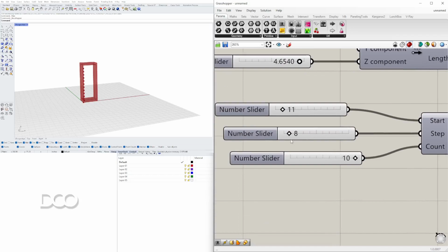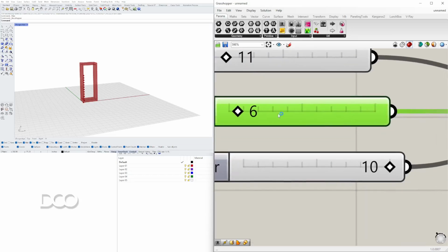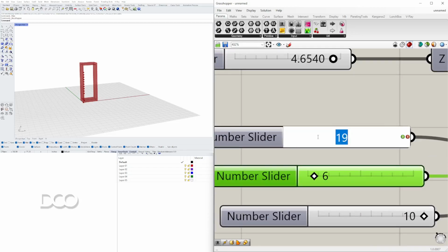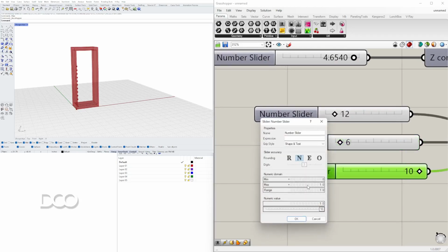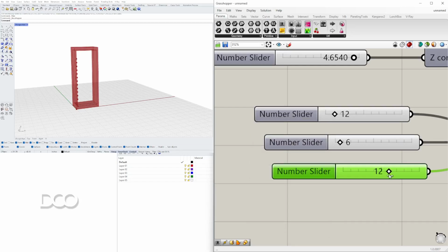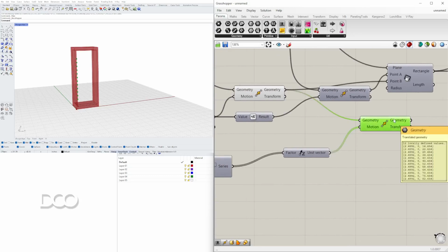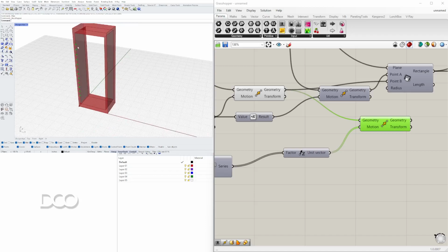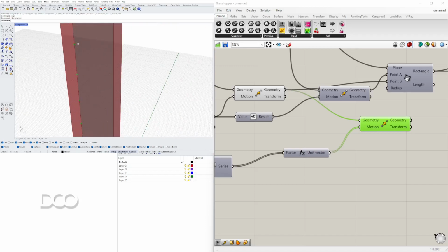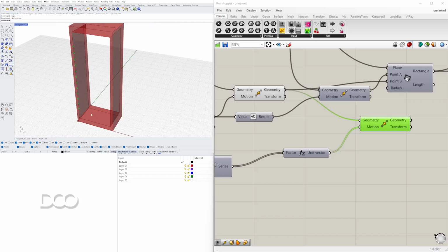And we can create more settings or smaller. So every 6 inches, starting 12 inches from the bottom, it's going to create 12. Now we'll max it out here at 20. We'll just say 12 points that it can create. So 12 points starting here, 12 inches below the bottom. What this will do is establish the points where we're going to create a solid and then subtract from the overall form. And this can take many forms. We're going to be using circles today, but it could be using different types of dowels and things like that.